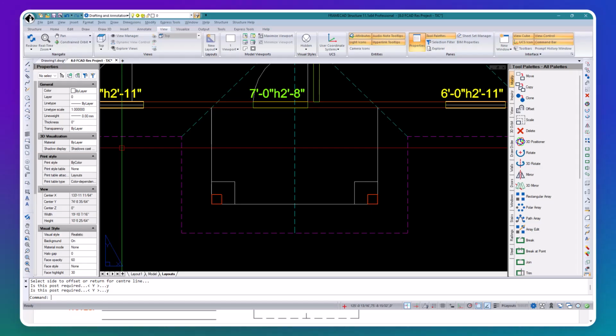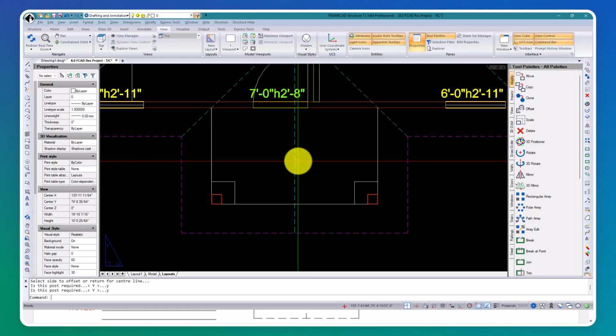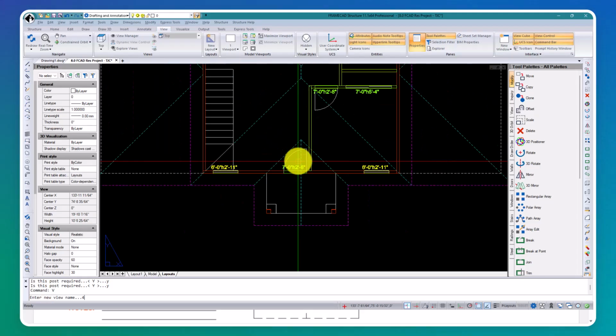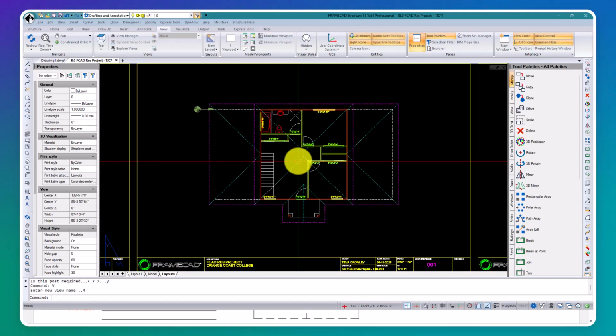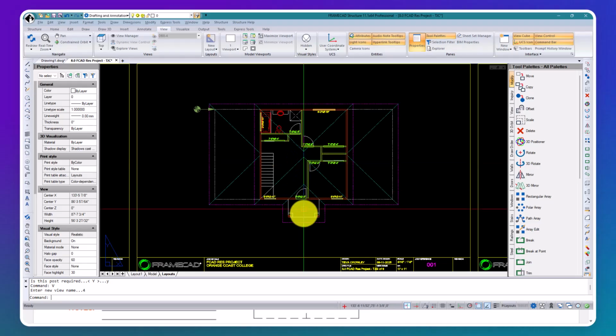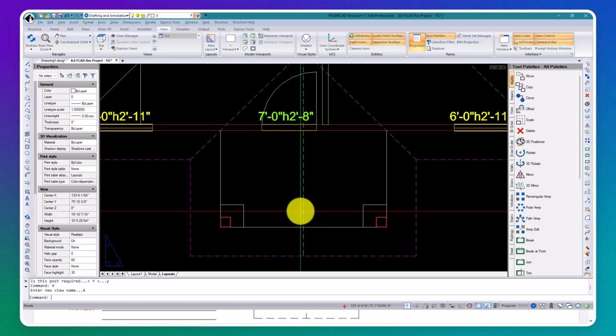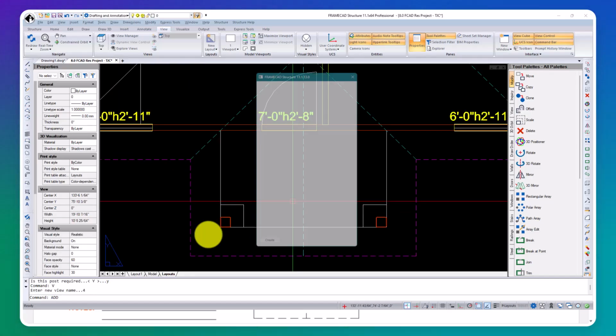Now we'll add the beams on the second floor that connect our balcony beams with our second floor walls in border number 4. Make sure you're in border number 4 by quickly navigating to it. Ensure that the second floor block is visible using the LT2 command as needed. Zoom in where the balcony is. Initiate the add framing command.